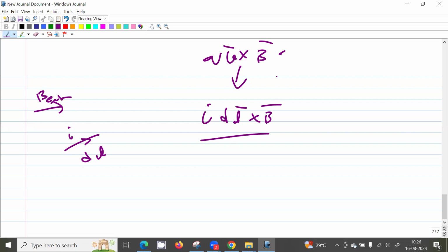The Lorentz force is the force on a charge moving with a velocity through the magnetic field. When you have a current, there are charges flowing inside the conductor, basically electrons. Each electron will experience a force, and each electron is the same because the velocity of all the electrons is the same, and the external magnetic field is also the same. So all the electrons will experience the force in the same direction to give a net force in a particular direction. That force is I dl cross B, and this can be derived.